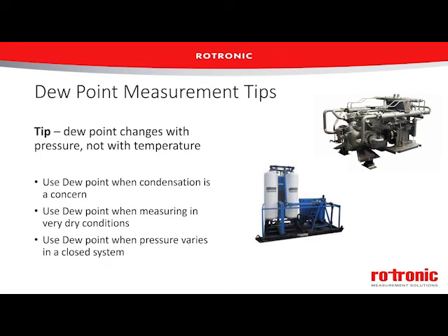Dew point or frost point is often used in applications where we're concerned about condensation. It's an easy way for us to understand if we're getting close to seeing condensation within our systems. We can look at the dew point temperature, look at the system temperature, and understand how much more cooling can happen before we're going to get that condensation.